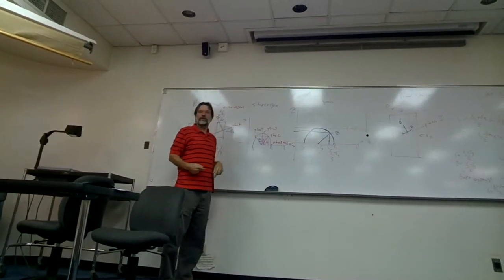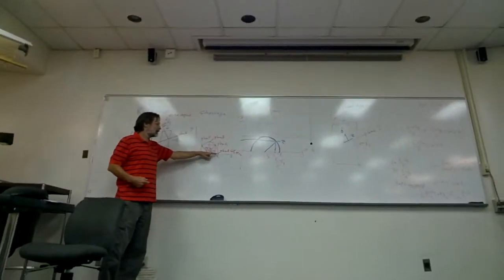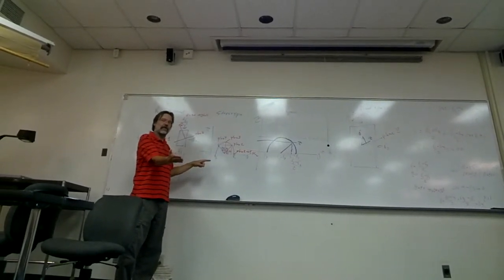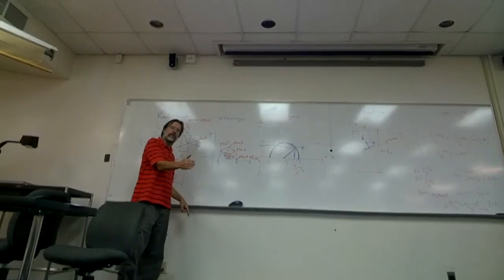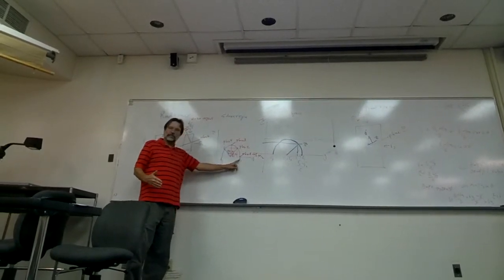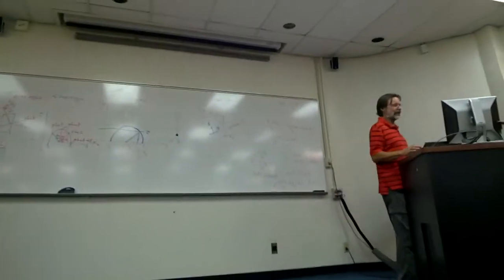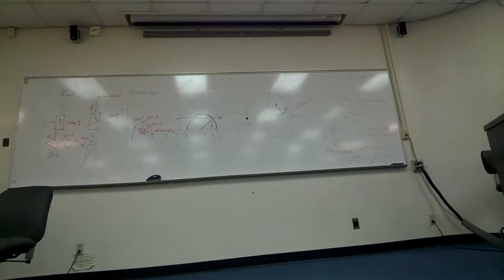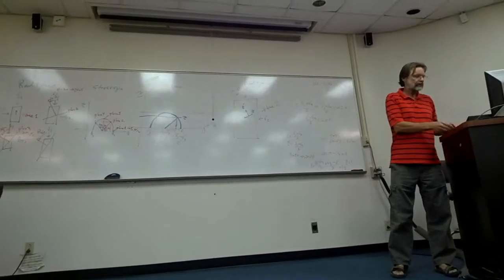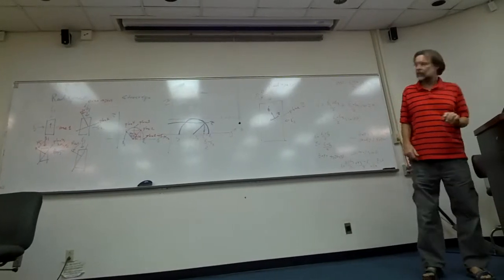That's the greatest shear stress, right? In all other directions, shear stresses first increase, if you consider this relationship. They increase to the 45 degree position, then they decrease as you continue to consider different orientations of plane, with the minimum pressure across this plane and the maximum pressure across that one. That's all there is to stress. There's a three-dimensional equivalent of this, you don't want to know it. But the point is, that gives you a qualitative feel, I hope, for the quantity we call stress that has these systematic variations.